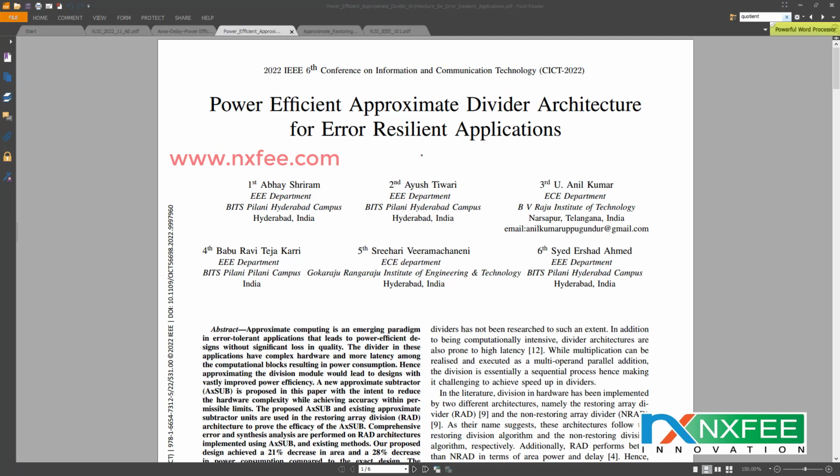In addition, the trade-off between the accuracy and the high performance for various approximate dividers is explored in order to determine which design achieves the best compromise. This is done to find which design strikes the optimal balance between the two complementary elements. The proposed architecture was created using Verilog HDL and synthesized with Xilinx Virtex 5 FPGA, and all the parameters were studied and compared with respect to area, latency and power.